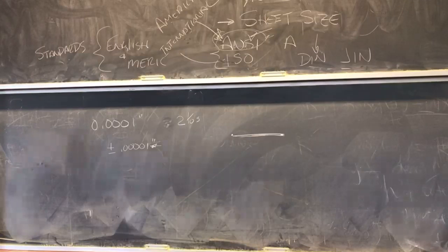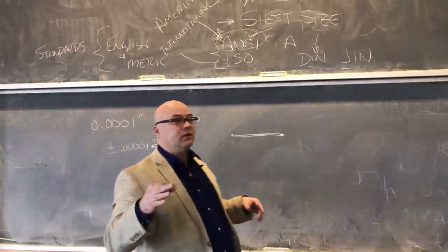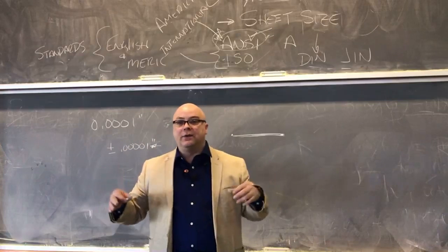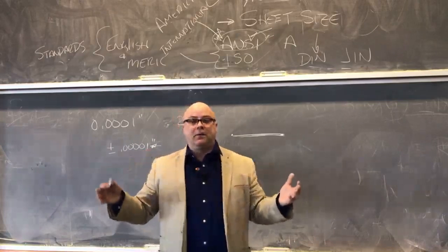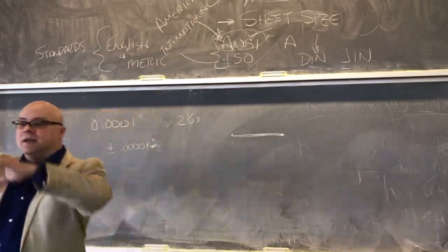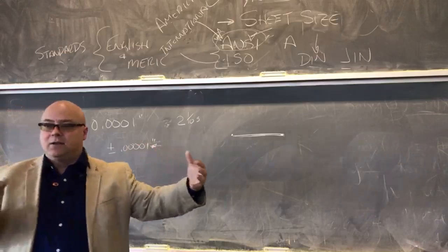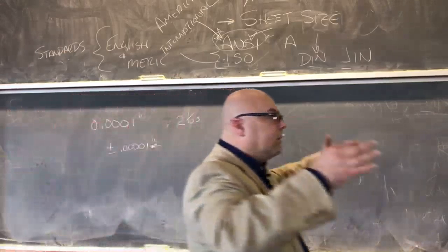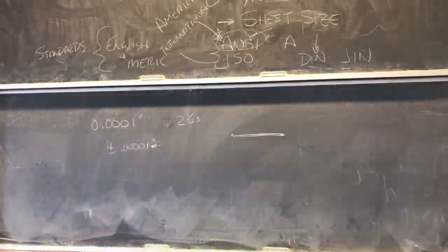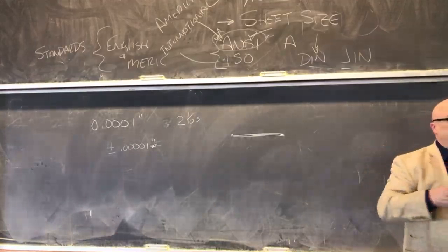So if you're the designer and you're choosing the tolerances, you may need to have a tighter tolerance. But what you want to do is tolerance on purpose. Remember last week we talked about functional design? We talked about understanding the customer's needs and defining the functions that meet the customer's needs before we do our design, right? So when we're doing our tolerancing, we want to tolerance correctly, not necessarily tighter.